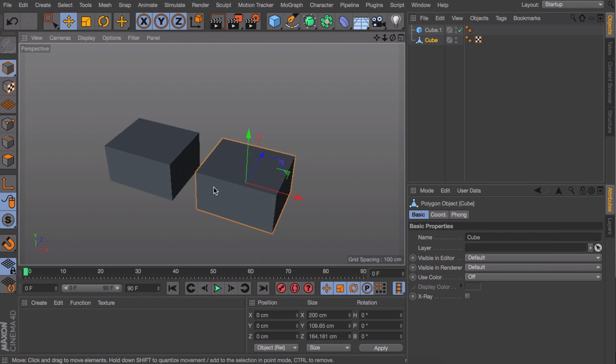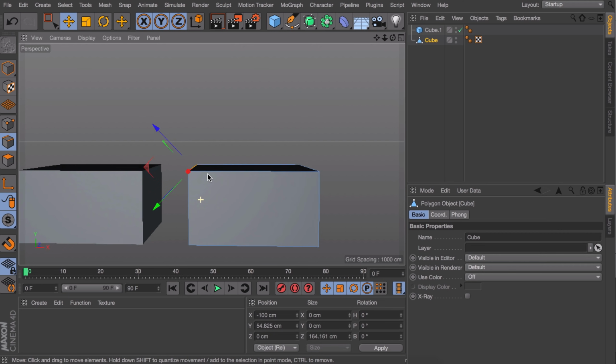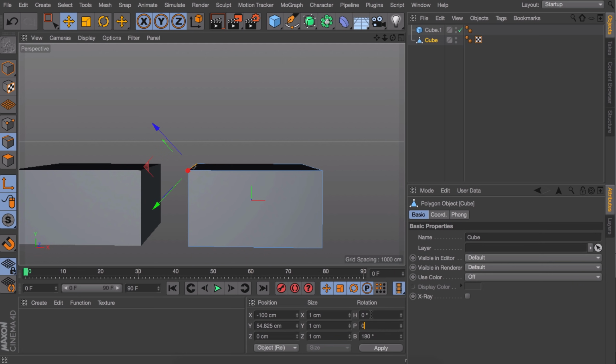We want to have these angled roofs, so we need to move one side up. And this can be done by enabling the edge mode on the side here. And now you can select this left one. But there is one problem before we can move on, which is that the move axis is pointing in the wrong direction for us. We will need to reset this first by going to the left again and enabling the axis mode. As soon as you've done this, you can see some rotation values down here. So just change these to 0 and hit apply.